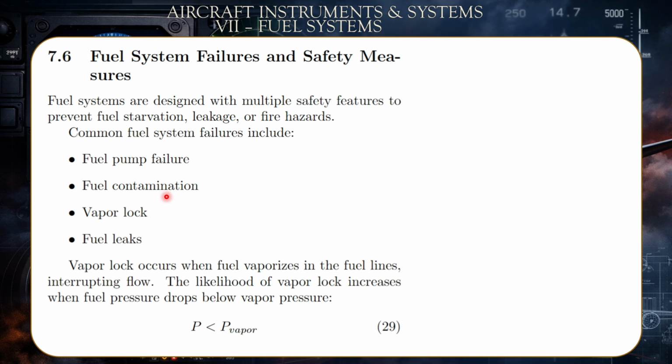consequences at times. Why? Because that can lead at times to fuel icing, okay, and excessive waxing due to the presence of water. Also, vapor locks, meaning that you could have vapor locked on the inside of the crossfeed that would keep the fuel from flowing from one part of the tank to another, from the left tank to the right tank, or vice versa.